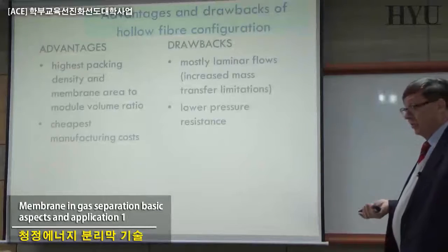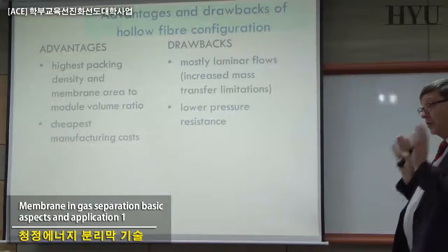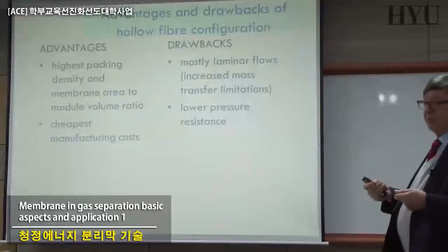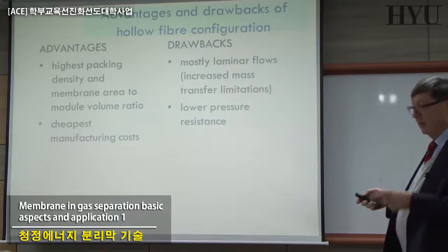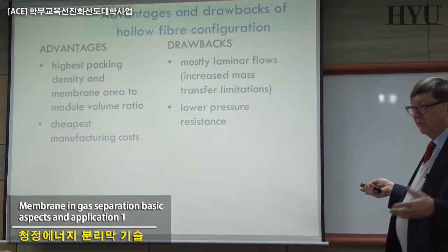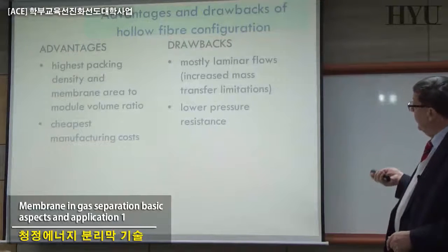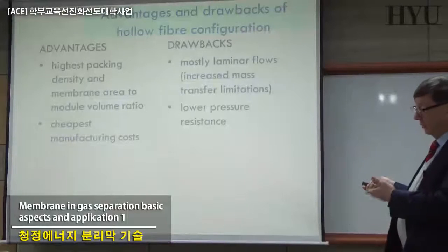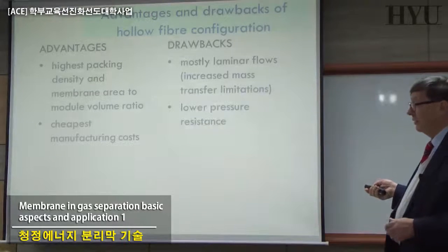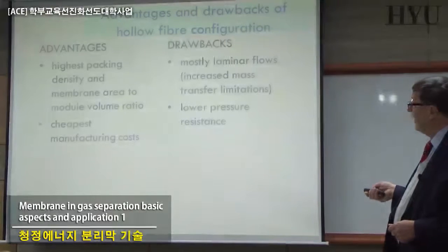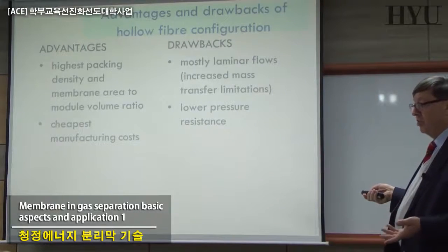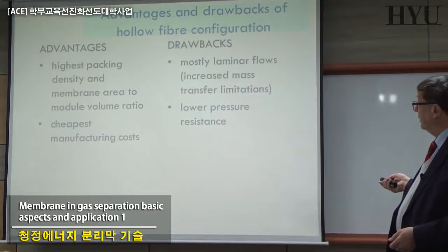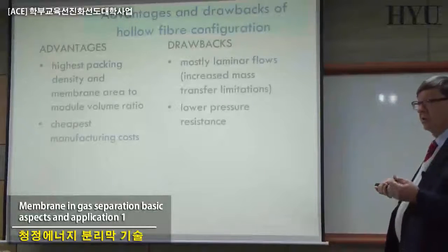Advantages and disadvantages of the hollow fiber: assume that most people here work with them, except when you do the first testing in the lab. As soon as you start to approach some interesting results for gas separation, you start to spin fibers, so you don't make flat sheet any more. And when you start to make fibers, the advantage is a very high packing density. That means the surface area is very high compared to the volume, and it is much cheaper in production, in handling, etc. The drawback is a relatively low resistance to pressure.